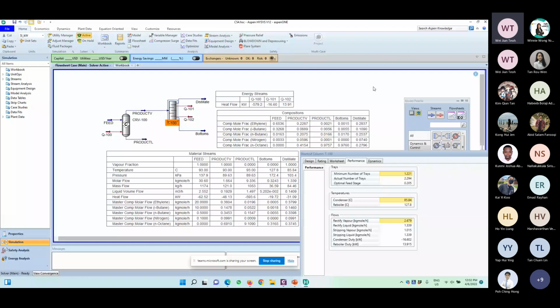So I can't answer this question without more information. You probably need to give me some more information. Or you can try that out by using a design spec or case study. You can actually try it out yourself as well. You try to change the concentration of CO2 in your inlet, I presume. Then you see what the reboiler duty is. That's what I can tell you.